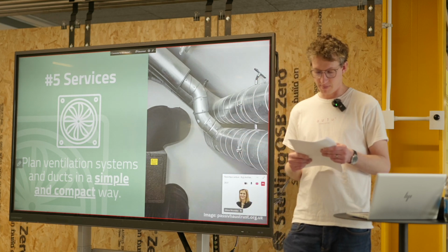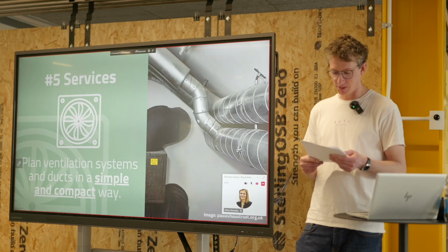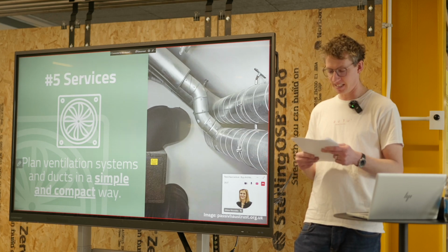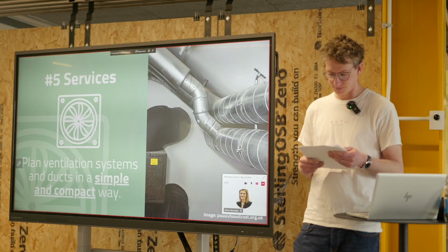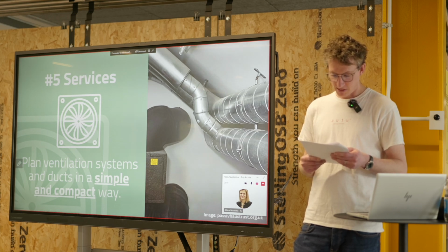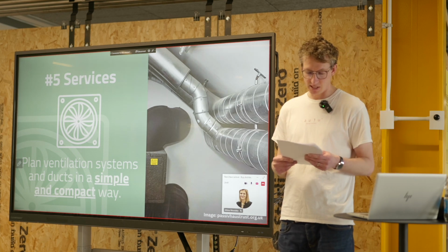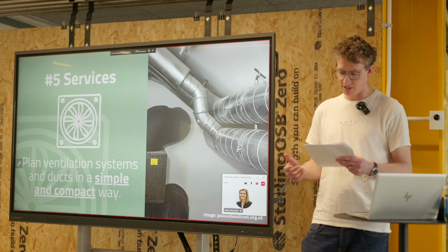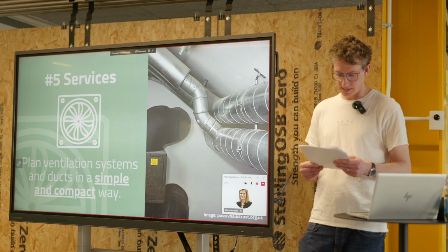There's so much information that I'm throwing at you here. I just wanted to give you a bit of an overview so you're aware of some of the considerations. And there's lots of information online as well that you can research and find out about these things in a bit more detail. See if I missed anything on here. Like I said, you've got to plan your air path routes through the building: which spaces are supply, extract, or transfer, and make sure you accommodate these things on the floor plans, basically.